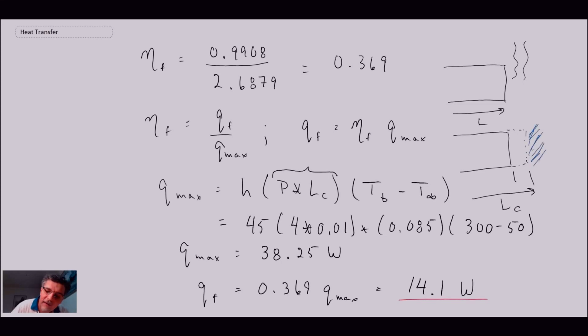So it's through this addition of this small area here and here that we're able to make that approximation and use the case 3 solution to approximate the case 2 scenario, which is the more accurate one where you would have Q convection coming off here. So that is solving a problem with fins, and that concludes